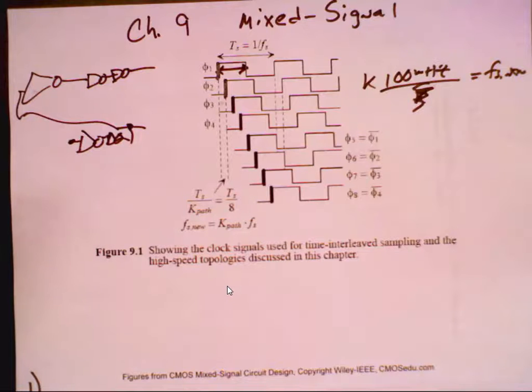I'm not going to ask you, okay, if I put the pole here and I move it by 0.01%. I'm going to ask you questions that say, well, what happens if I run this slow? What happens to the integrator? What happens to the overall feedback signal, those kind of things. Is anybody unclear about integrator saturation?